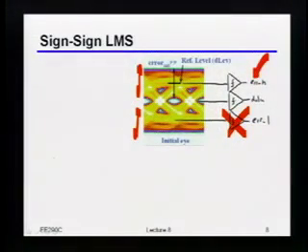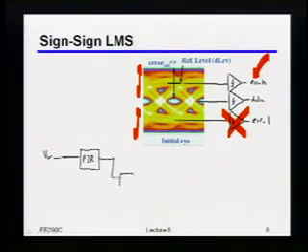Yeah. Like we did before, like a peak detector. Okay, that's true. You could actually do a peak detector. So I think what you're saying is do something like, take your analog input that, let's say, is going into, well, I'll just draw it as a block here. That's feeding into your FIR. And then basically do, like, let's say, a peak detect over here. And then feed that in as the reference for that other comparator. You could indeed do that.